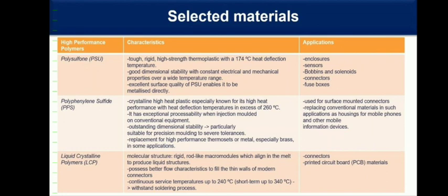Then we have liquid crystal polymers or LCP. There we have a special molecular structure, so you have to imagine you have rigid rod-like macromolecules which align in a melt, and so you have liquid crystal structures which have a self-reinforcing effect. You can imagine it similar to glass fibers.